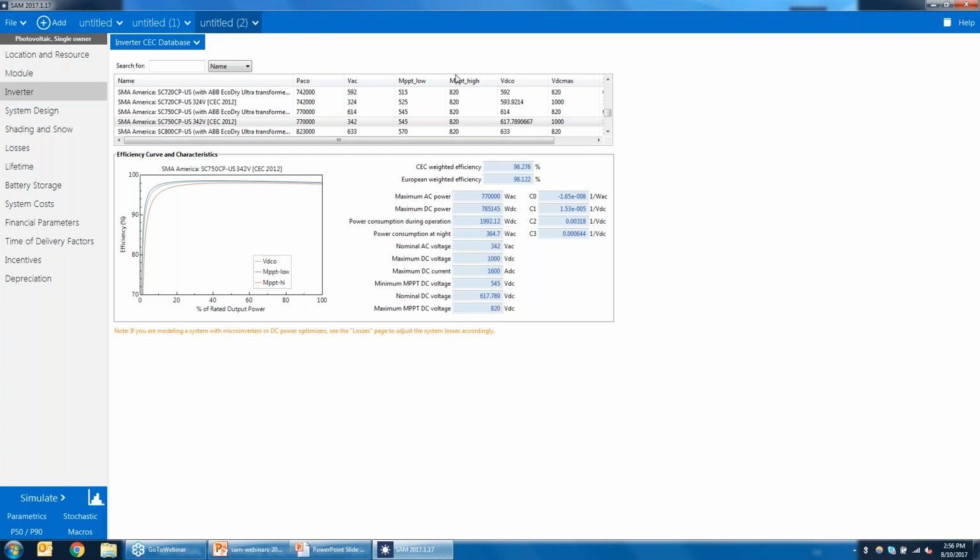So here's a follow-up GCR question. How do you cap land area when optimizing GCR? So you could find the optimal GCR for a given roof area. There isn't a way to constrain SAM for a given roof area or ground area. So you kind of have to run the model iteratively and try different GCRs and look at the resulting areas to do that kind of manually.